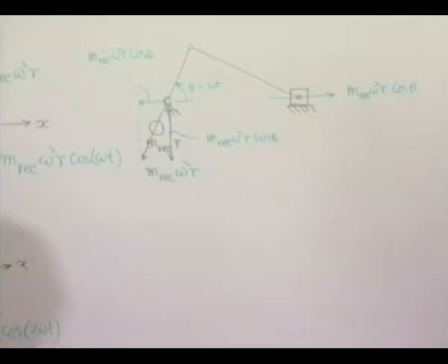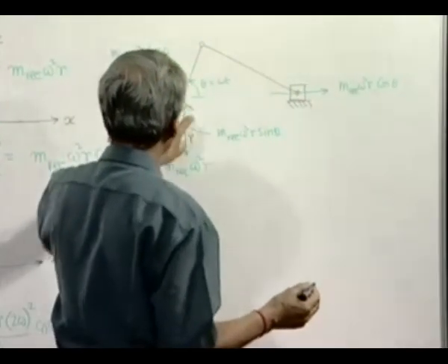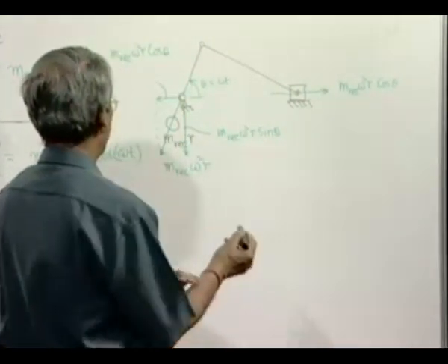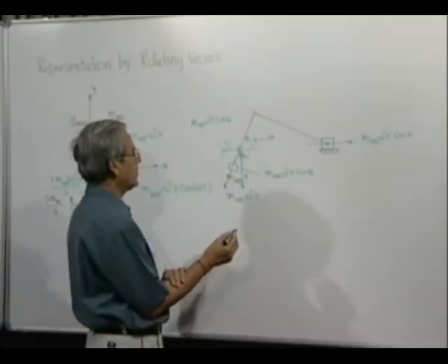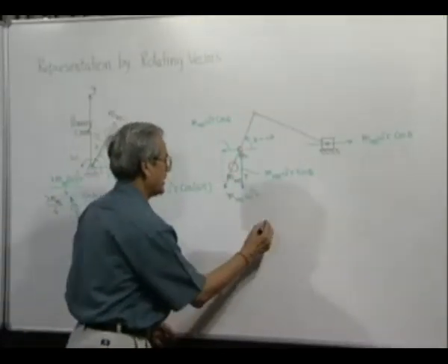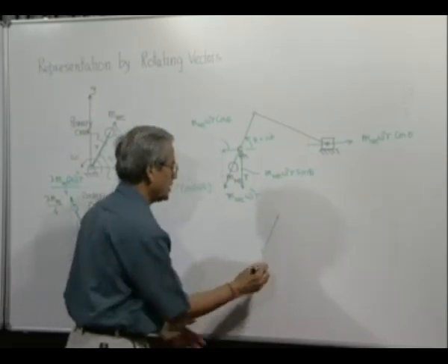Now, the actual original unbalance due to the reciprocating mass and the centrifugal unbalance force produced by this balancing mass attached as a counterweight, in effect, the resultant system will be now subjected to an unbalanced force which is in the y direction.